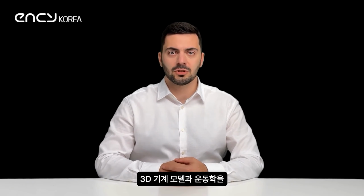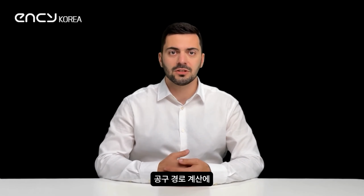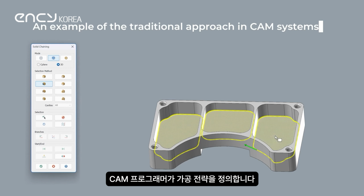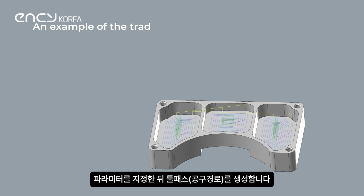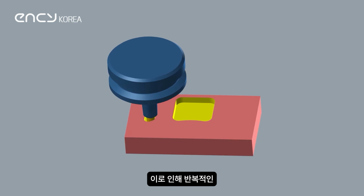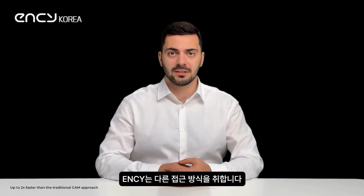Machine awareness. Unlike many CAD/CAM systems that use 3D machine models and kinematics only during simulation or post-processing, ENCY integrates the machine's digital twin directly into the operation setup and toolpath calculation right from the start. Here's the traditional approach. A CAM programmer defines a machining strategy, selects tools, sets parameters, and generates a toolpath. Only during simulation do problems like gouging, collisions, or axis overtravel become apparent, leading to a repetitive cycle of adjustments and resimulation. ENCY takes a different approach.